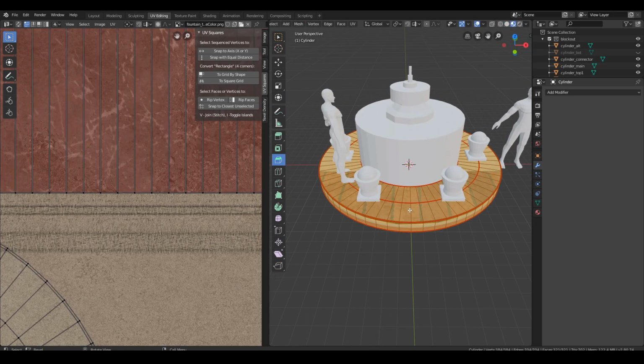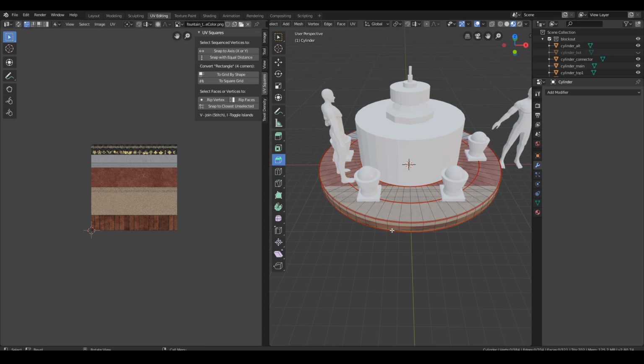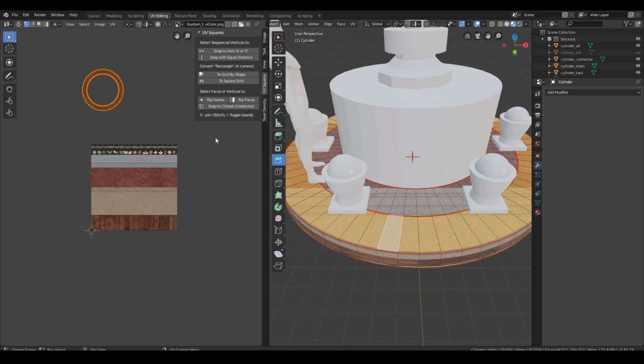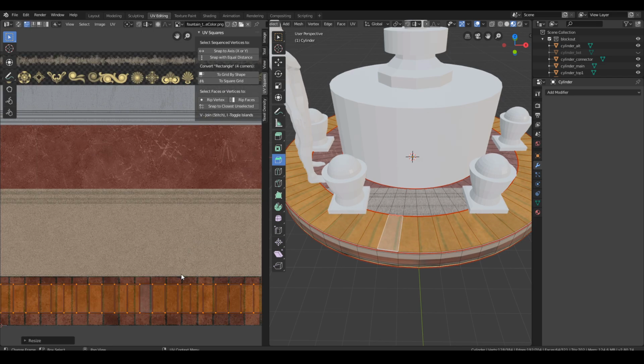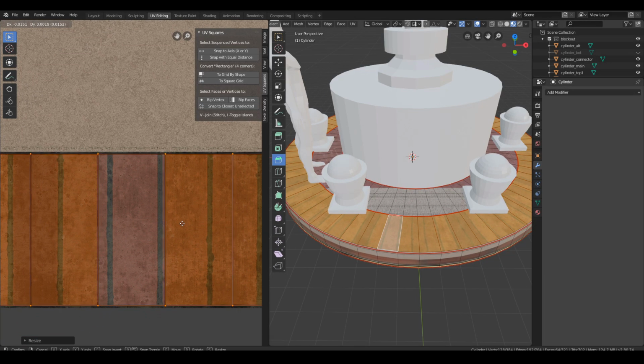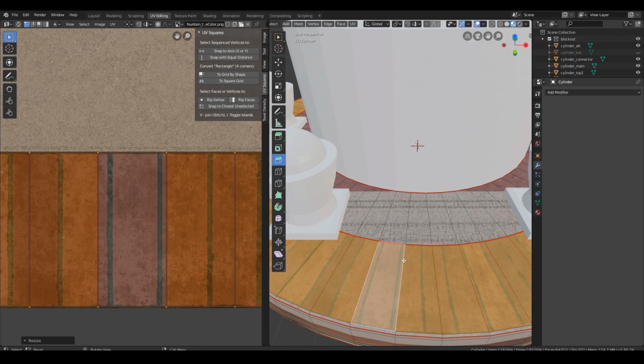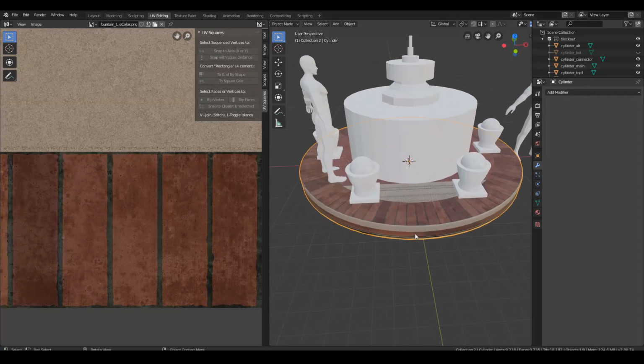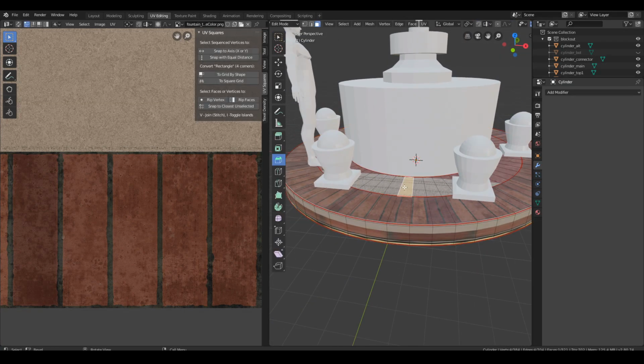Now go to the UV Editing tab, and here we also enable the third shading option. You can select all polygons within the seams by using the L button and then the U button to unwrap the selected area of the mesh. Using the UV Squares window, click the Grid by Shape button. Thanks to this, we will change our surface into one horizontal strip.